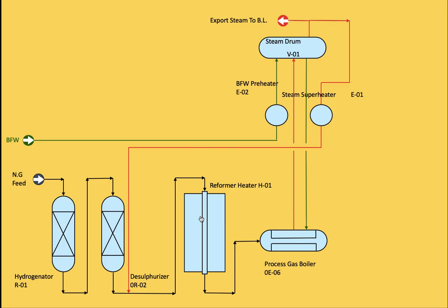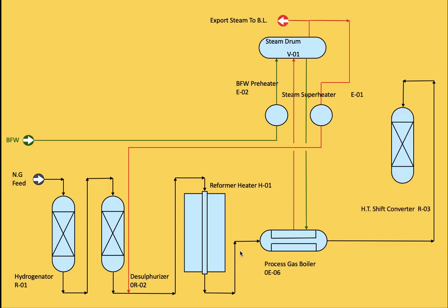Does any other reaction happen? Yes. For example, if there is a C2, C2H6 plus 2H2O, the steam, will give you 2CO plus 5H2, hydrogen. And the outlet stream here is too hot, so we need to apply the heat recovery principle by producing steam using boiler feed water. The outlet temperature is around 350 degrees C.